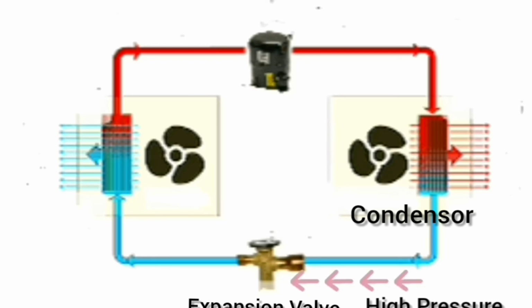For the expansion valve to operate efficiently, the refrigerant coming to it has to be 100% liquid. So to ensure this, the liquid refrigerant is subcooled, which means that the temperature of liquid refrigerant is lower than the condensing temperature at the pressure it is under inside the condenser.